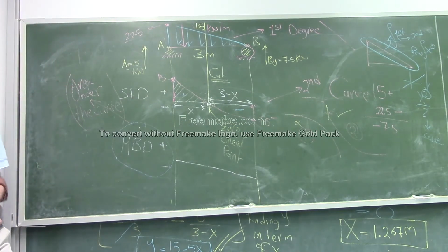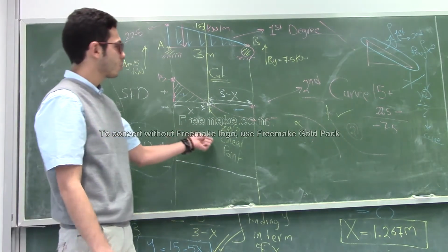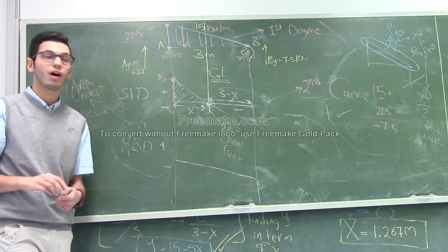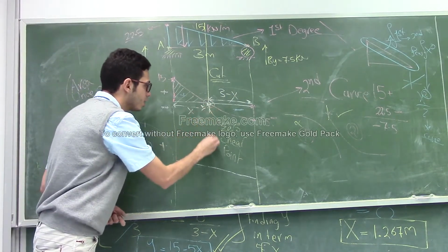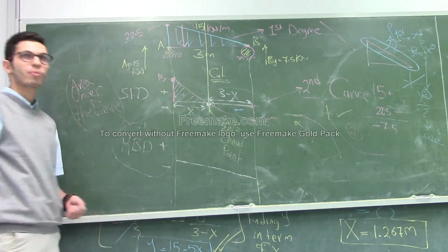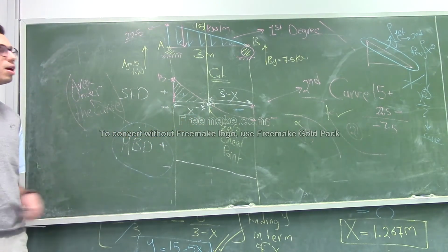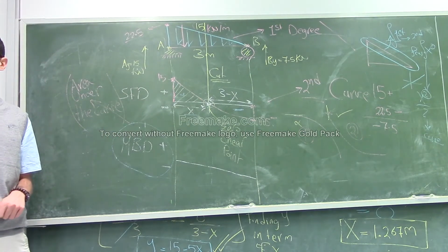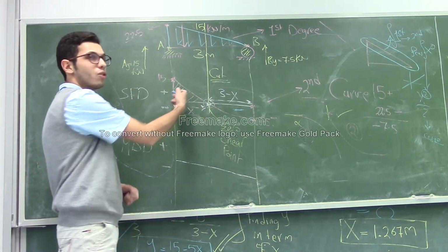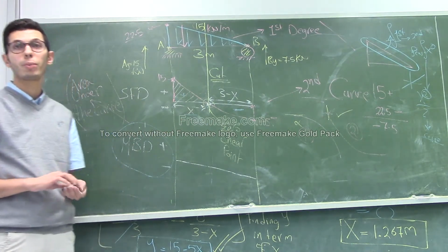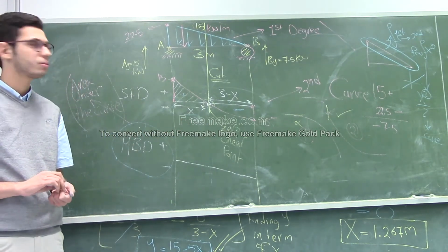Okay. So now, after we find the distance x, we should find the moment. After we know this x, the moment concept is the area under the shear curve, right? Can anyone tell me what is the area for this shape? It's 1.267 times 15 times half.